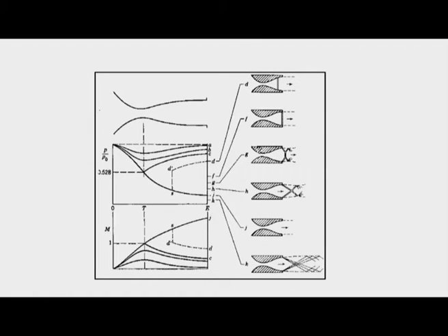This is the reservoir condition, then we have a convergent divergent nozzle, and then this is the exit condition. Let us pretend that the reservoir and the exit are both at the same pressure. If both are at the same pressure, there will not be any flow in the nozzle. But now, if we decrease the pressure at the exit, then flow will start. Initially this convergent portion acts as a nozzle for the subsonic flow.